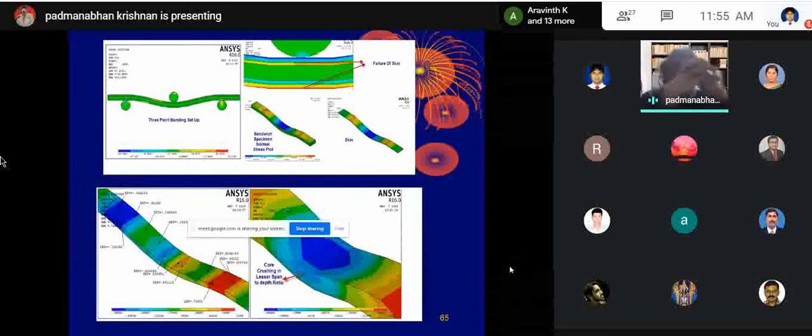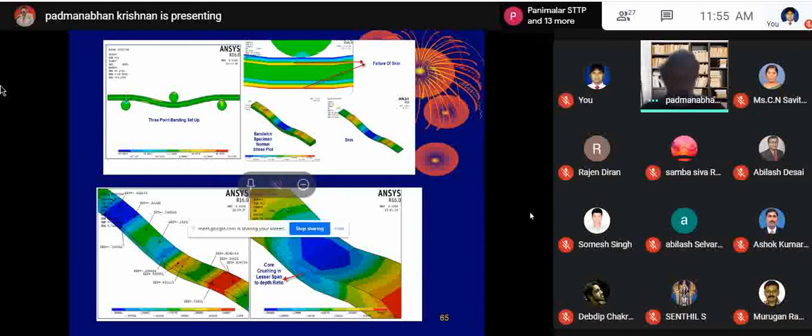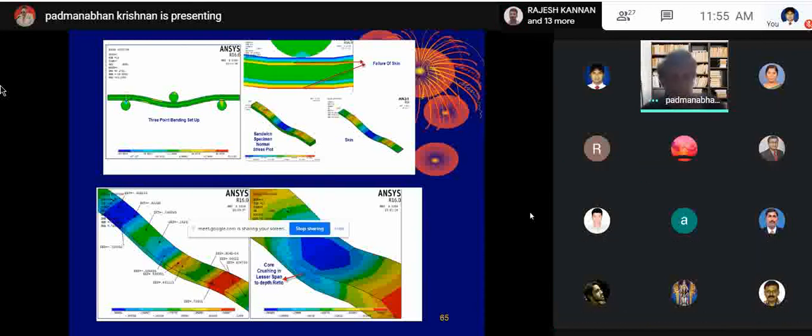it's best for stiffness. Now when we checked it for foam composites, we found that the optimum was actually around 2.5 to 3.5, and then it varied with density, with volume fraction, and also with the thickness of the foam, because in the thickness of the foam you have what is called shear flow. You know what is called shear flow. The shear flow is nothing but the shear stress multiplied by the thickness.